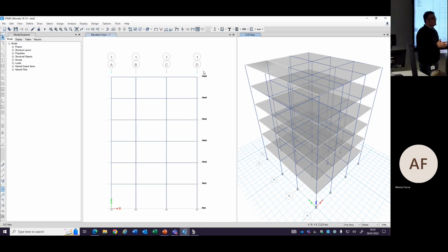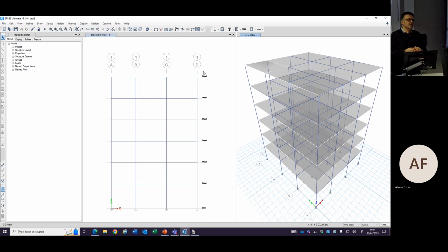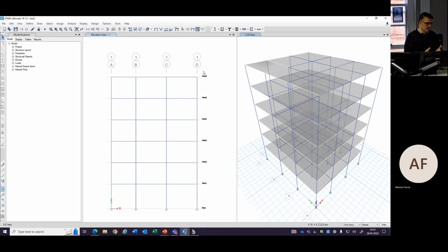If you have done your coursework, you saw that you need to take one of the beams, bring it out to see what the load combinations are, and finally, for any kind of element, any kind of design, you will come up with a demand to capacity ratio, isn't it? What is the demand in terms of shear? What is the capacity in terms of shear? In terms of axial load, in terms of bending?